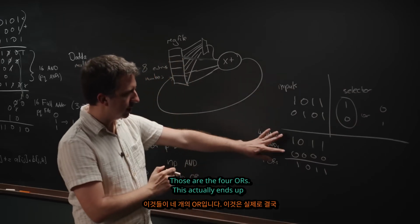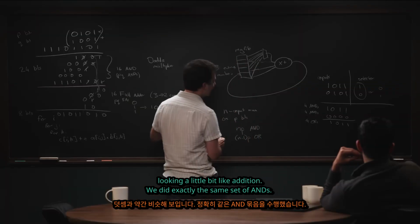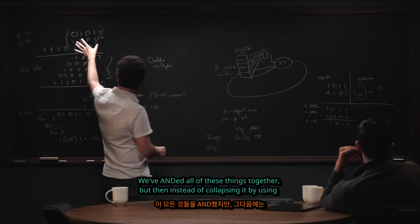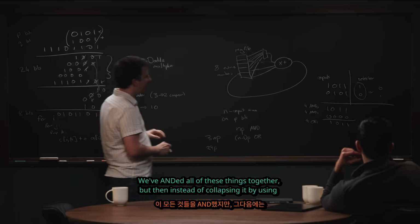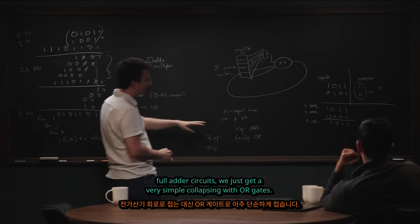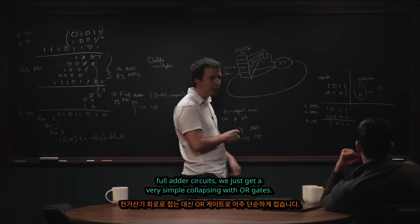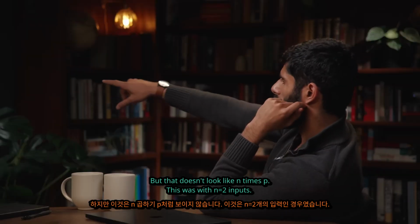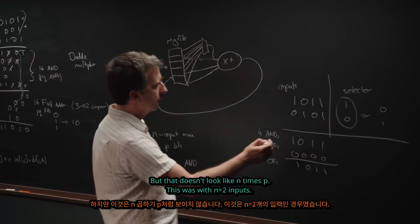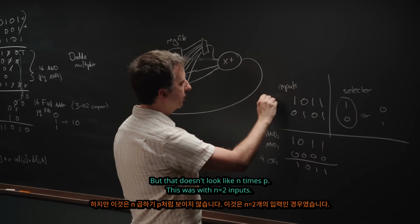So this actually ends up looking a little bit like addition, in fact. We did exactly the same set of ANDs here. We've ANDed all of these things together, but then instead of collapsing it by using these full adder circuits, we just get a very simple collapsing with OR gates. But I guess that doesn't look like n times p. So this was with n equals 2 inputs.